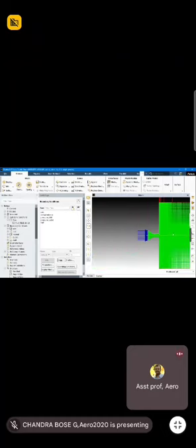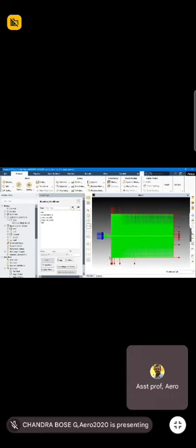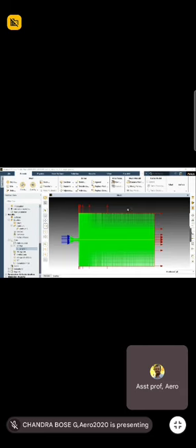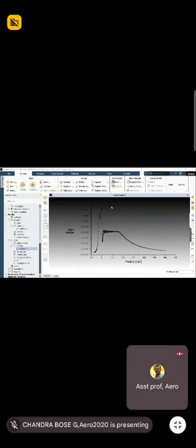Far field, it is very sparsely spaced. How to move this, sir? How to move this? Okay. We will show one case how to make the single center line pitot pressure. We have to go to the plot, go to XY plot, and then first we will see the velocity in Mach number. Axial Mach number. You can see the axial Mach number.